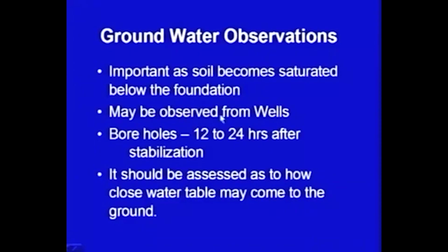You can get it from the wells or from the boreholes which are advanced during the exploration program, and for that at least 12 to 24 hours should be given for the water table to stabilize. After the water table stabilizes, the water table depth should be measured. And it should be assessed how close this water table may come to the ground or to the foundation. That is what we should assess from the field exploration program.